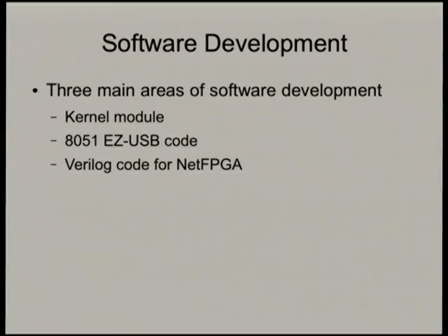Okay, so looking at the software, there's basically three areas that need development. There's the kernel module to drive the USB interface. There's the code that runs on the 8051 microcontroller on the EZ-USB devices. And there's the Verilog code, which is by far the most complicated part of it for the NetFPGA.